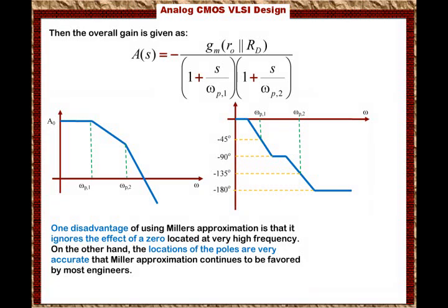This concept is studied in controls, so make sure that when you use the feedback amplifier, the op-amp is stable. The phase margin is roughly selected to be anywhere between 60 and 40 degrees, which means that you are 60 degrees away from 180 degrees when the amplifier reaches unity gain or 0 dB.